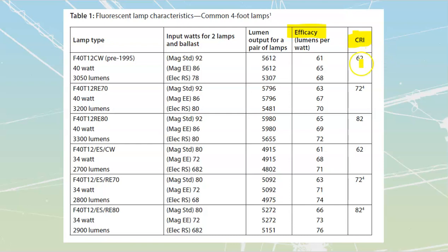So the higher the CRI, the better the look that I'm going to have. What they use as the CRI reference is outside daylight, the sun. That's our most natural light that is out there. So this one over here is going to be about 82% the same as the sun. Most of us don't recognize it very well, particularly among males. We've got a really high incidence of color blindness. So 82% to 100%, those colors would probably look identical to me. But I can definitely tell once I get down to something like a 60 CRI that everything just seems a little bit off inside of there.